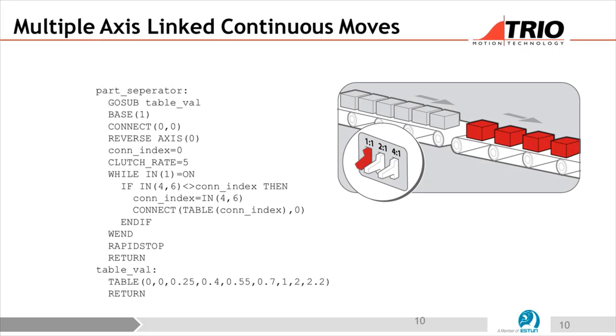This is the example that is in the project that's on the notes. But what I'd rather do is if you just open up Motion Perfect and open up the terminal and have your axes enabled, so you can make sure the watchdog's on and the servo's on in an axis that works. This is for Hoy, axis 1 in your case. So have the drives enabled, have the servo on, so that it's ready to go.